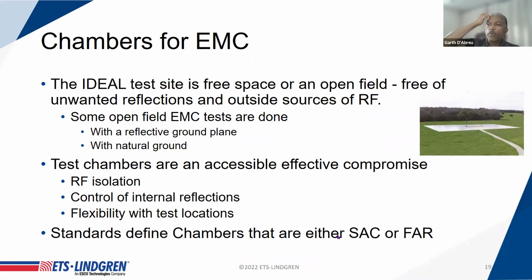And of course, the open area test site, or OATS, I think was the original RF test environment, from which everything sort of spawned. So everything is referenced back to an OATS or an OATS-type environment. And this is characterized by a free field, obstruction-free layout with a reflective ground plane, with good propagation characteristics, with no reflections from any external structures.